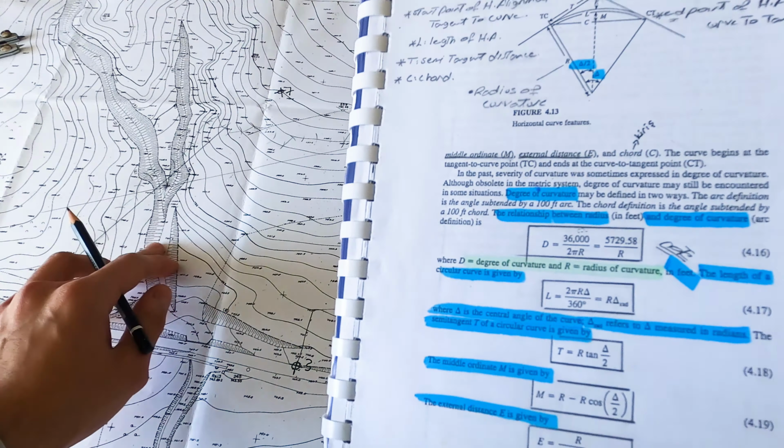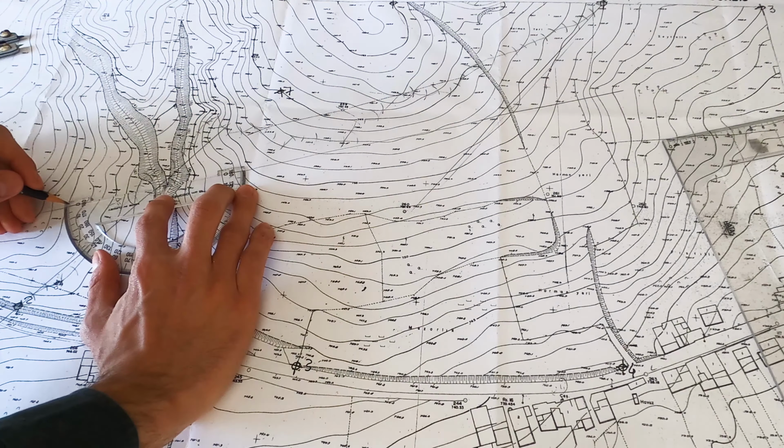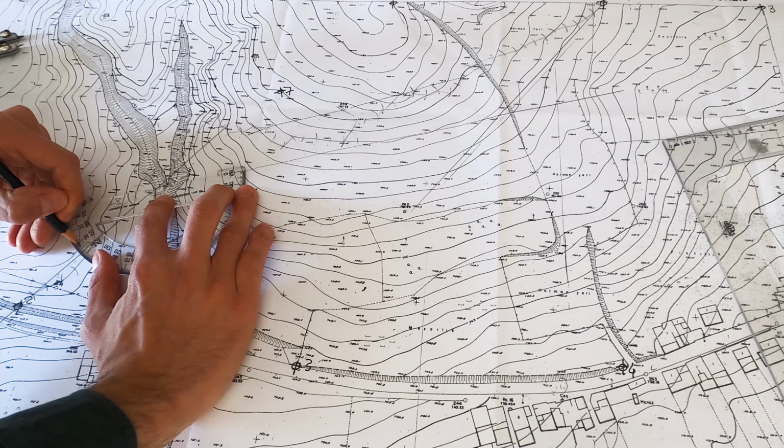How to compute delta 1? We have to use this ruler. This one. We take the center of it on the intersection point here. The 2 points, it's very important to take it on the line in order to get the correct angle here. We put the center of the ruler on the intersection point. And starting from 0, this is 30, 35, 36, 37.